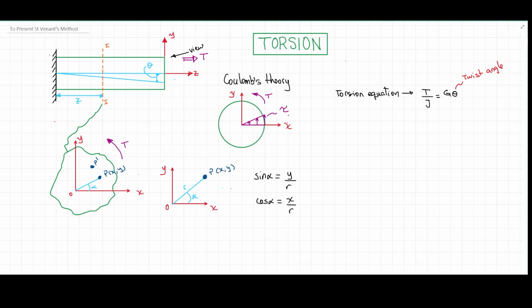Then when I apply this, of course, this is going to be rotated, kind of following some sort of arc. But as it is very small, this arc can be considered a straight line here. And it's going to be a straight line that the path is going to be 90 degrees with respect to this one. But in any case, the important thing is that according to St. Venant, the whole formulation, when you apply torque on a non-symmetrical section, two things happen.